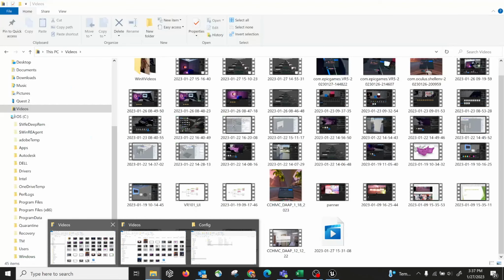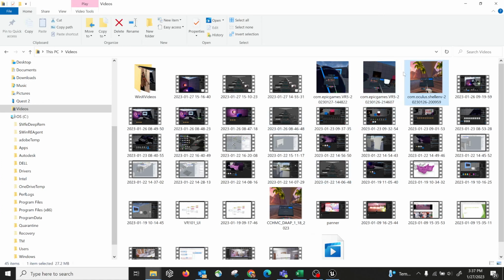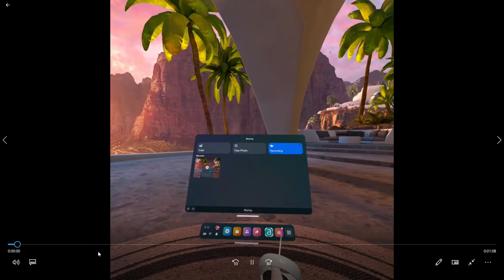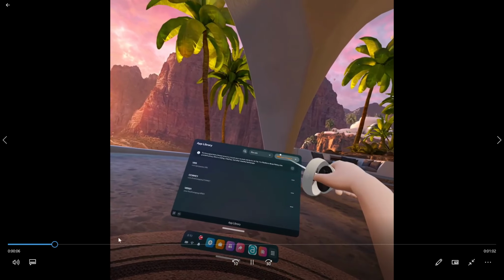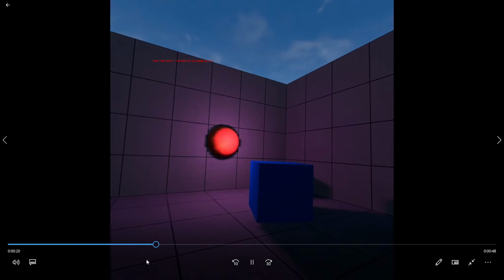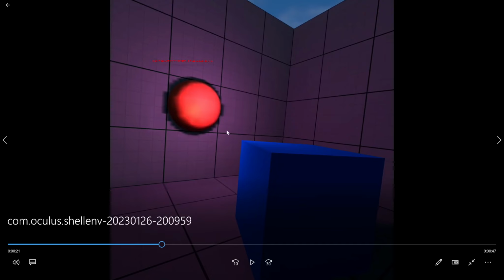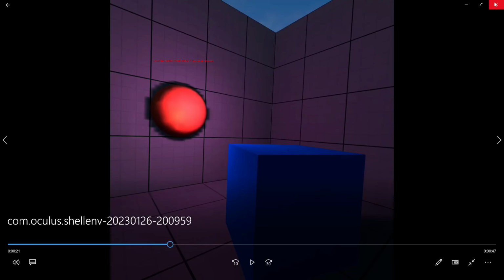And here I can show you the video. This is a video I captured of the various combinations of these rendering settings. So this is the package produced without using forward rendering, right? Just the default render. Here you can see once I log in, everything looks fine, but this IES light profile is not being loaded correctly, right? So that's one of the reasons you do want to turn on the forward shading. Otherwise, this IES is not correct.